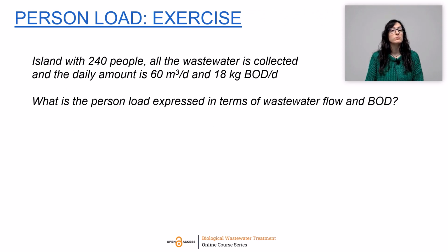Let's do now a small exercise to put into practice what we have just learned. So imagine that we live in an island with 240 people and we collect all the generated wastewater. We know that the daily amount that is being produced is 60 cubic meters per day, and we also know the associated organic load, which is 18 kilograms of BOD per day. Based on this, we have to calculate the person load in terms of flow and in terms of BOD.